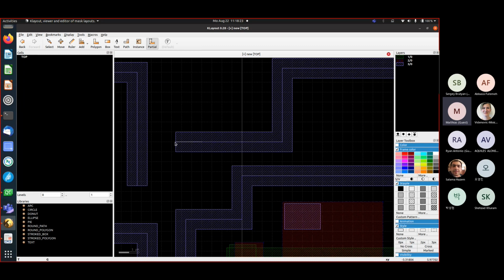But now if I click there, I can change the first point. You see, while I do so, the path loses its Manhattan property. But what I can do is also shift. Shift will only move the point vertically and horizontally, which will still make the path kind of skewed. But what I can do is I can also shift the whole segment.